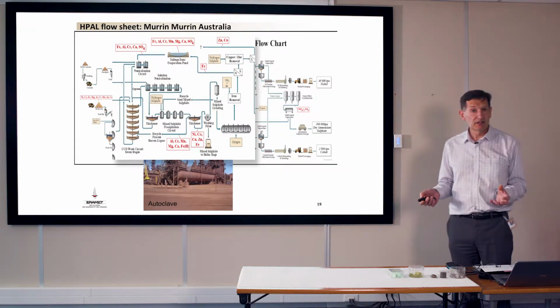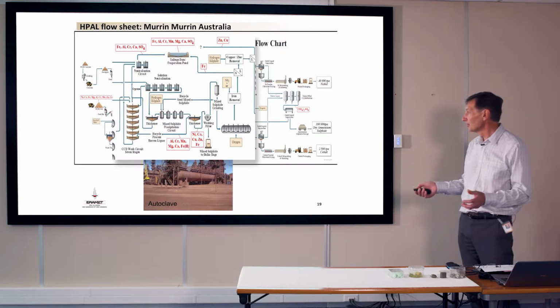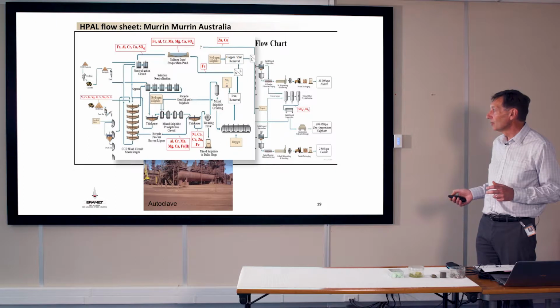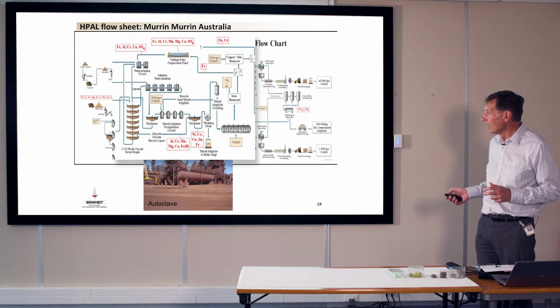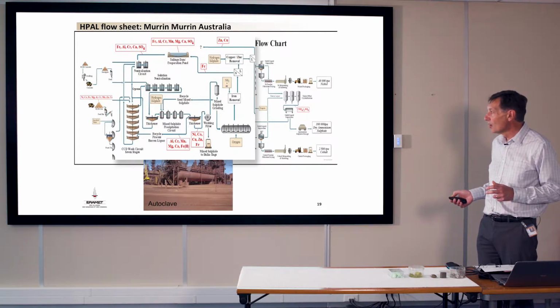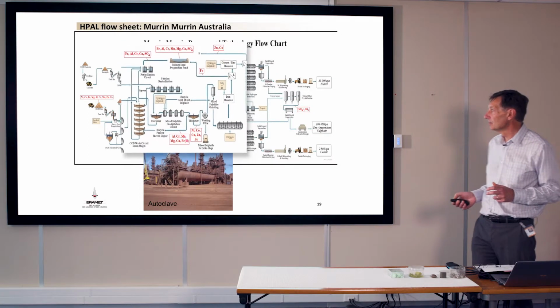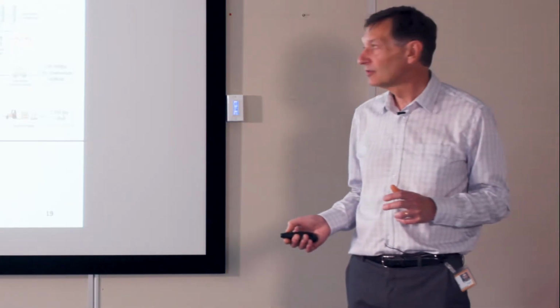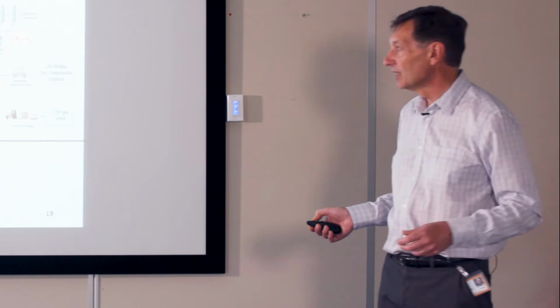It's an intermediate product. The choice of this process is to have a solid intermediate product, mixed nickel cobalt copper zinc iron sulfide, and to leave in solution the other impurities, aluminium, chromium, manganese, and magnesium, that are put in the residue and put in the tailings. That's the first part of this flow sheet, the front-end plant.